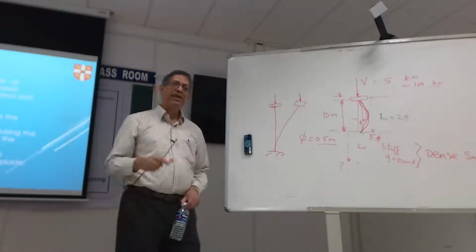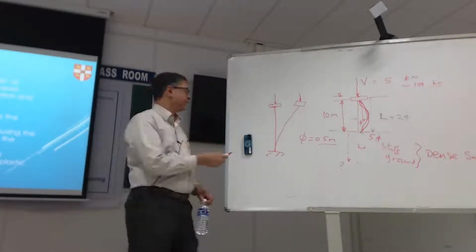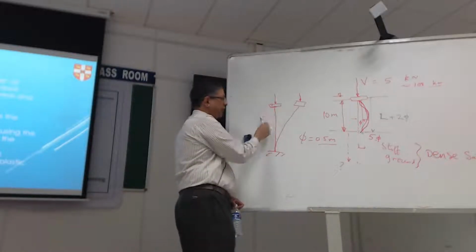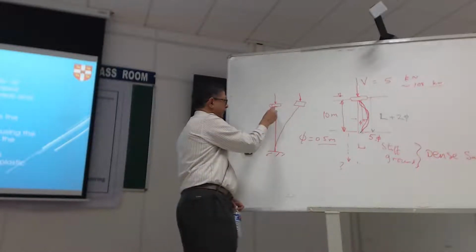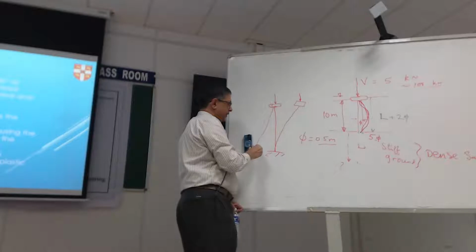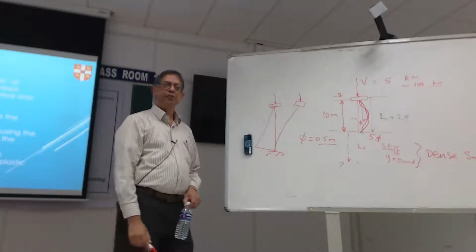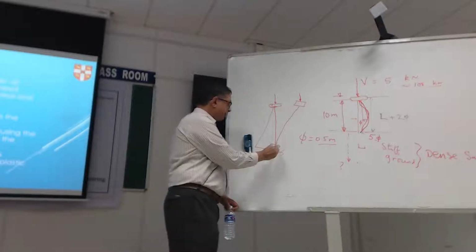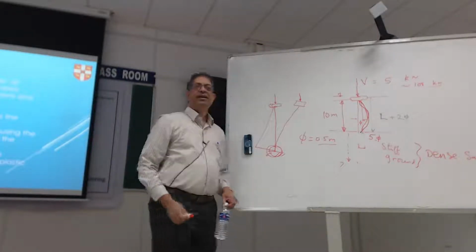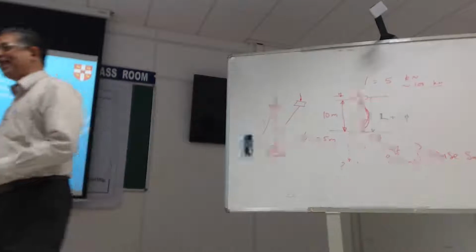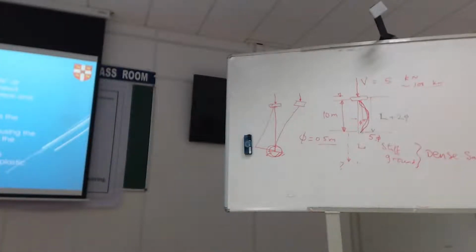And if you plot the bending moment for this, you'll invariably get a bending moment which is increasing by that. Yes? Which means the largest bending moment must be here. If the largest bending moment is at the base and it increases as the pile buckles more and more, how the hell is the plastic hinge formed up there and not down here?